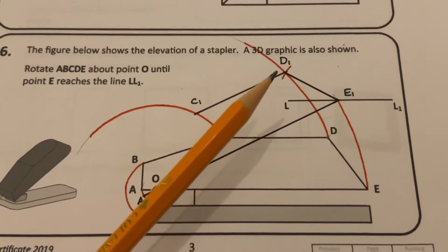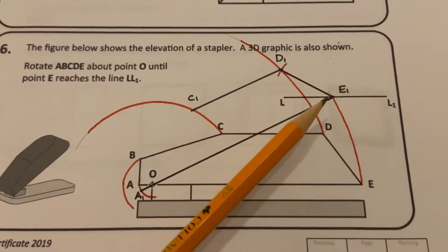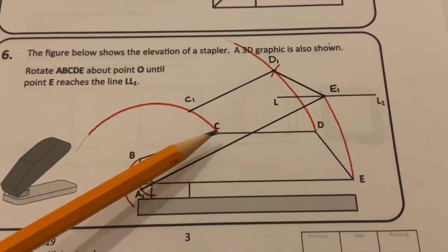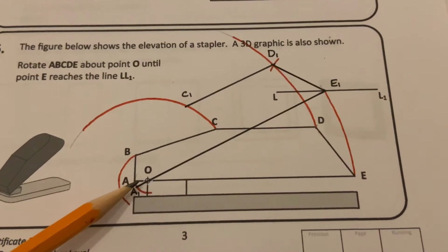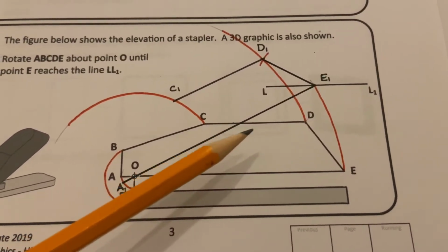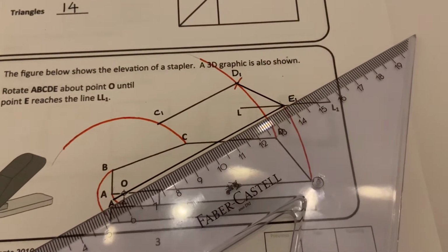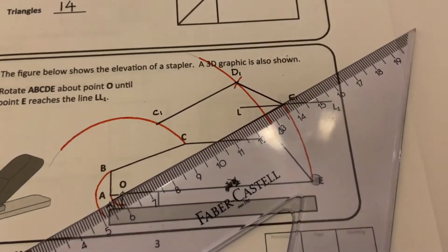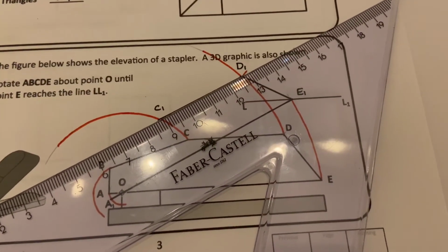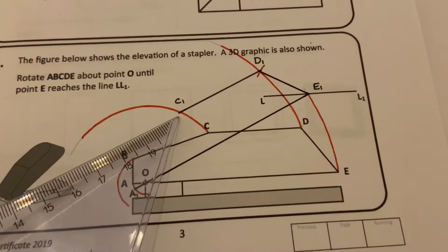So after swinging the distance there from E up to D, it gives you this point here, and then we can connect a line from E1 to D1. Now if we look down here, we can see that this line CD is parallel to the line going from A to O to E. So this line and CD are parallel. So taking your set square and using sliding set squares, line up your set square there with OE, and then slide that out there accurately and draw a line from D down to the arc that C is on, and that locates C1 in this location here.